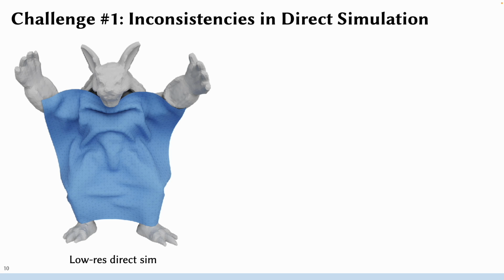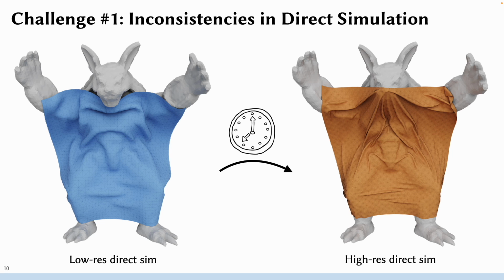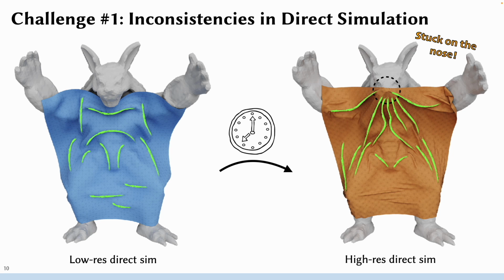Well, to enable progressive simulation, there are a number of challenges that we will have to overcome. One obvious approach is to design a scene using a very coarse-res interactive simulation, and then, once all material and layout parameters are finalized, finish up the simulation with a finer resolution mesh. But this immediately runs into trouble. You could say part of the fine sheet got stuck at the armadillo's nose, and moreover, low-res and high-res wrinkle patterns do not match with each other.